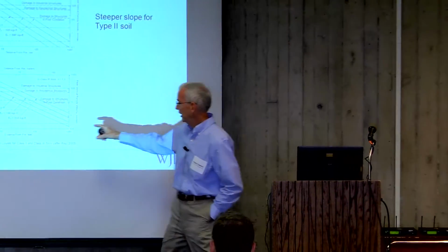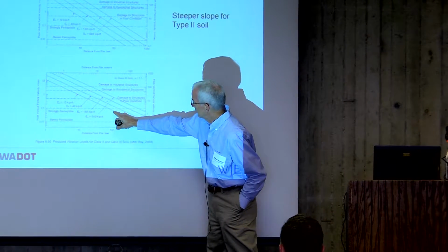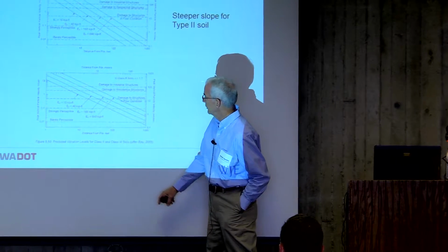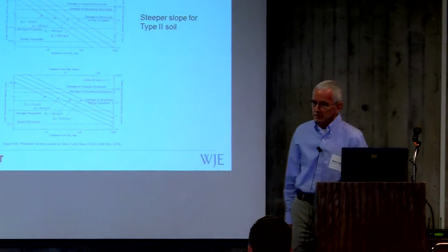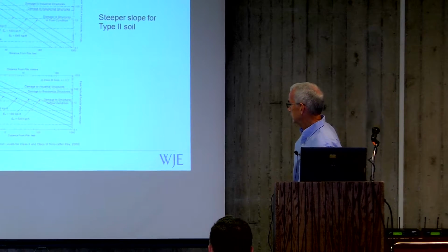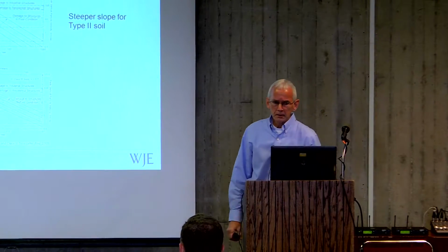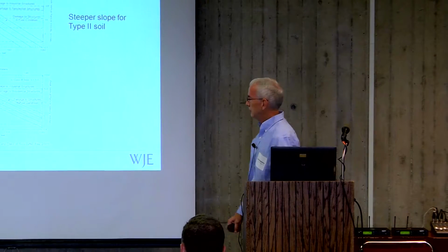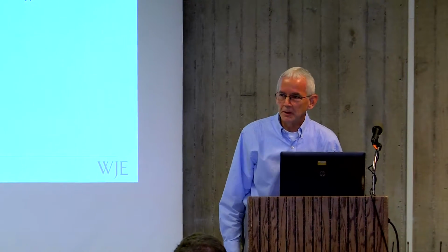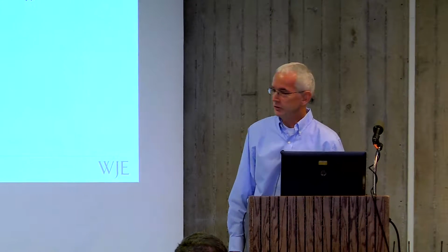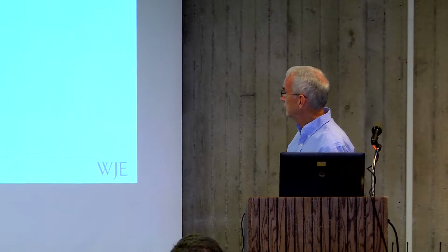So at a higher energy hammer, up to 640 kip-feet, you'd get significantly higher vibration at a given distance of 100 feet. For the low energy hammer, you'd be about 0.08 inches per second. But for the 640 kip-foot hammer, you could get up to about 1.2 inches per second. Well, no, like 0.9 inches per second. But that gives you an idea of the fact that there are significant differences in the soil type and how that comes into play, and something that you would have to take into account when you're trying to estimate the effect of vibrations on the surrounding buildings.